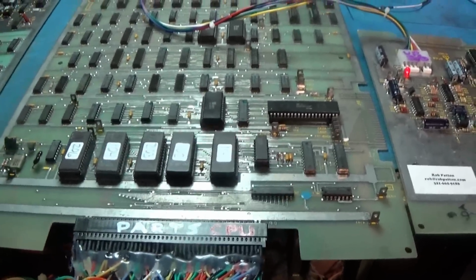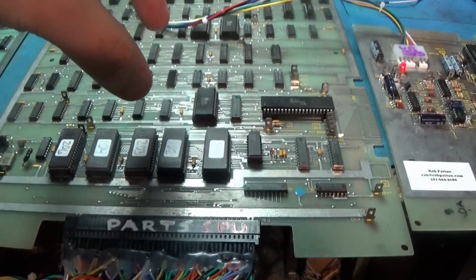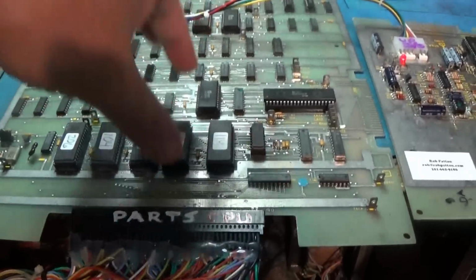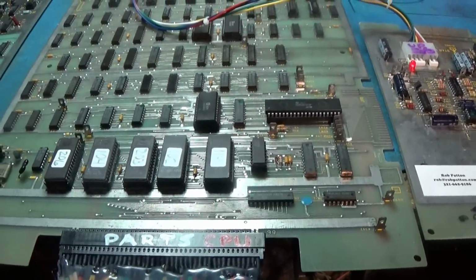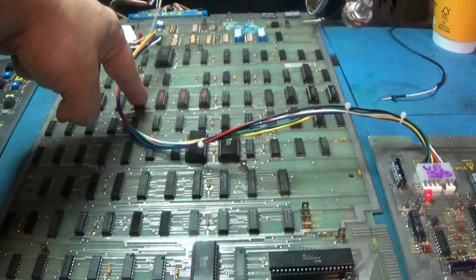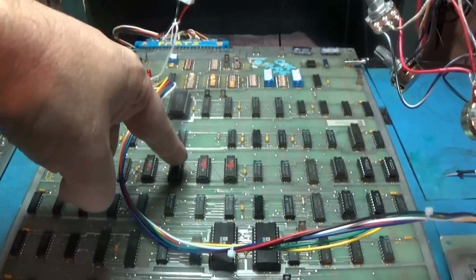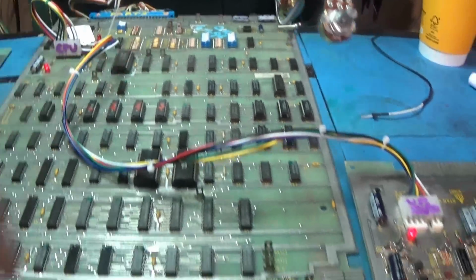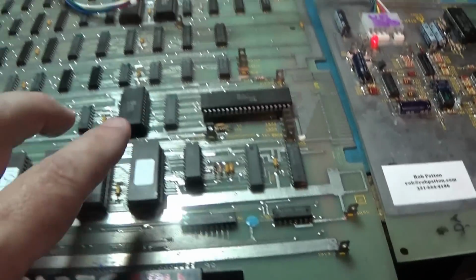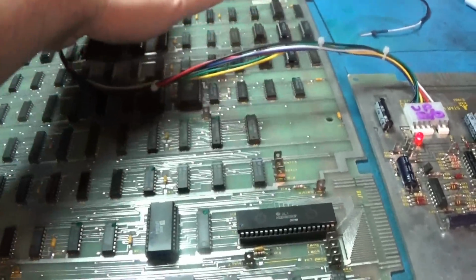That kit from Atari came with a little board that plugged in, I believe, right here, and it had a couple ROMs on it and a couple ICs. It also came with new bipolar ROMs up here for Empire Strikes Back, so I had to burn new bipolars for Star Wars, new Star Wars ROMs, and I replaced all of these sockets.